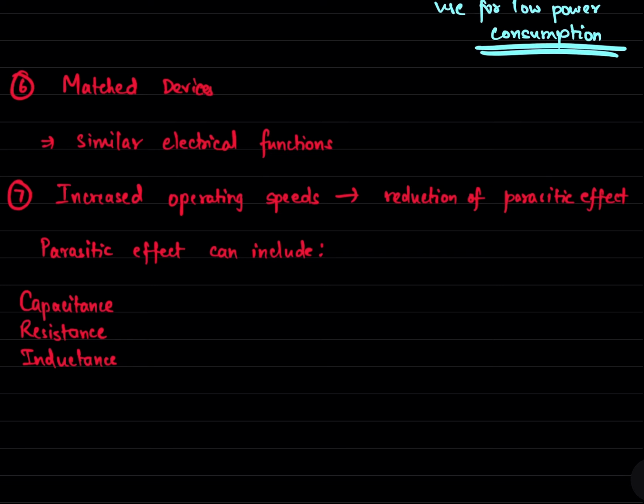Inductance, and so on and so forth. Parasitic capacitance is nothing but a capacitance which exists between the conductive elements in an IC, such as a metal connection joint and semiconductor substrate layers, etc. The parasitic capacitance stores and releases electric energy, which causes delay in the signal propagation.